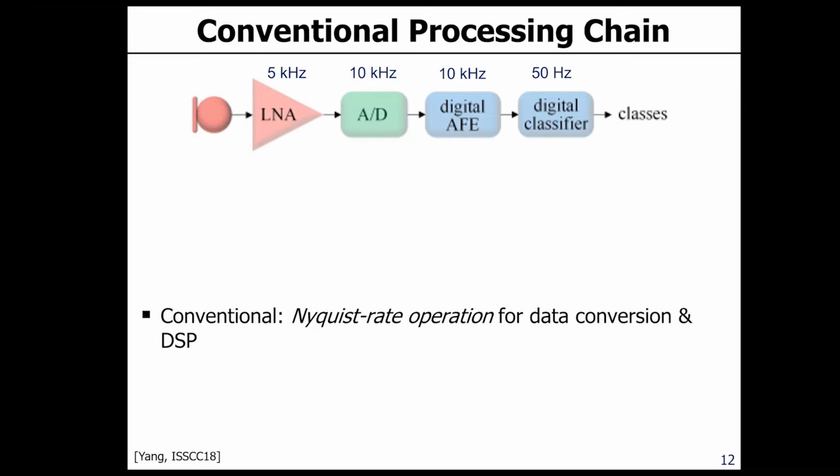The reason is, if you remember, I showed the spectrogram a few slides ago, right? This spectrogram is not a sample-by-sample thing. It is actually over a 25 millisecond window or even a wider window. So in other words, the digital classifier gets new input at a much slower rate than the signal samples, right? So the digital classifier, in the end, is operating at a much lower frequency. It's not the clock frequency. You can still have a higher clock frequency by reusing your hardware, but the data rate that it produces is much lower than all the other three components that we have.